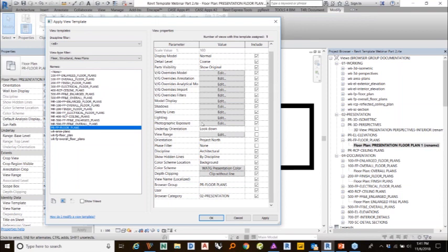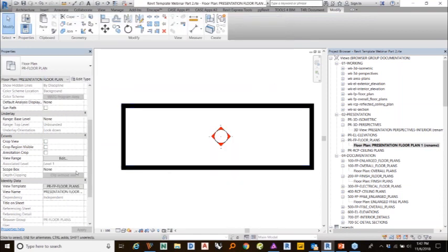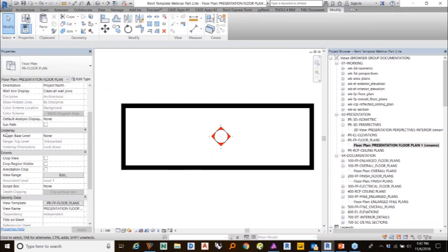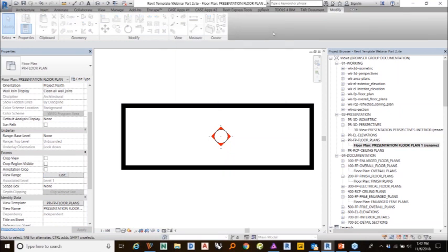So what this means is that if I go over here, I have activated my underlay options here as an analog sort of instance-based kind of way of attacking my view. I've also activated my view range, so I can manually change it here rather than in the view template. And so what this does is it allows me to have some kind of flexibility in that view template.